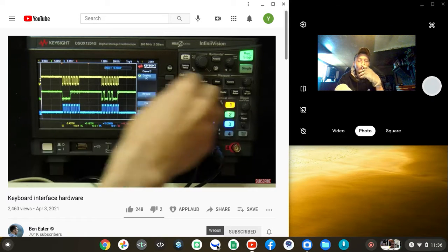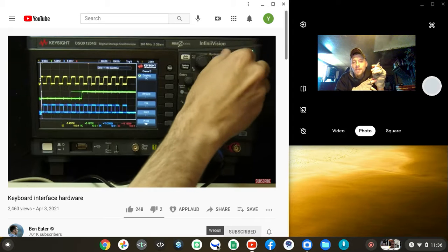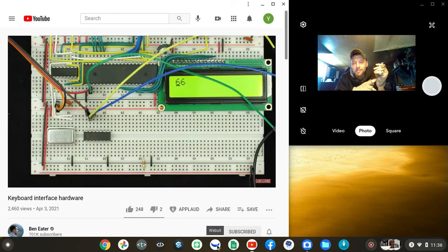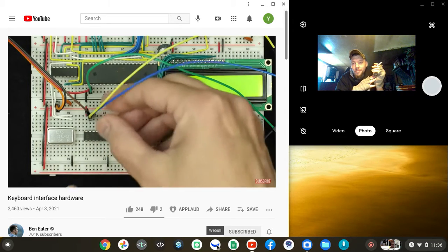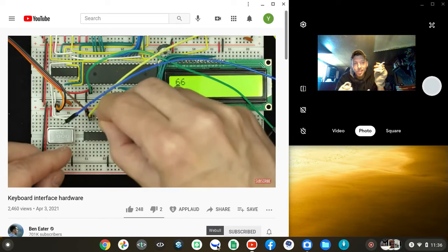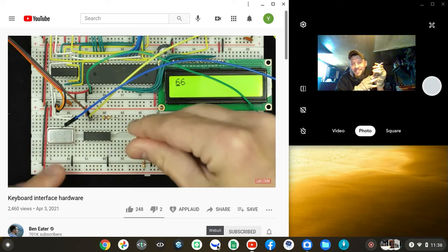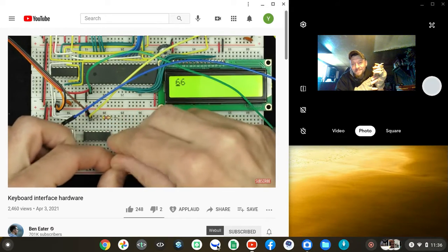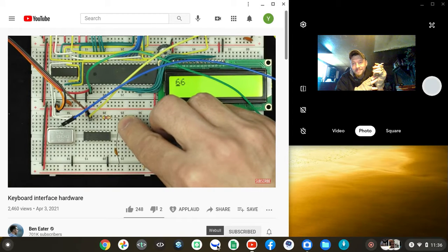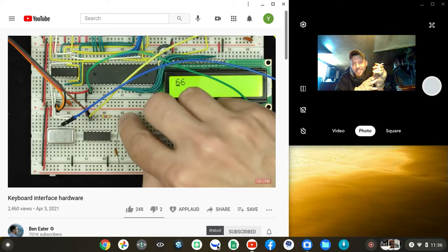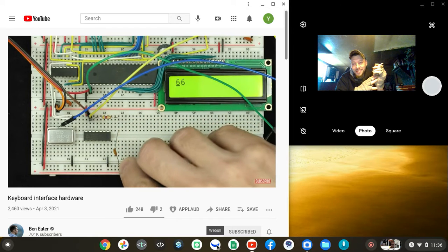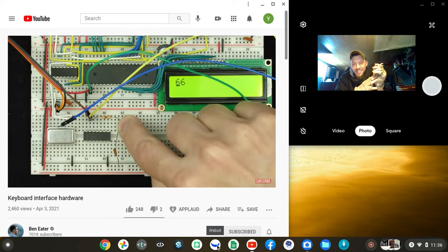So that's just the same as the clock pulse, but it's inverted. So let me zoom in there. So we're looking at a single pulse. And now what we can do with the output of this inverter is run it through a resistor and then a capacitor to ground. So when this clock pulse goes high, all of the current flowing out of that pin will flow through the resistor and essentially into the capacitor to charge the capacitor to ground. And so this point here will start out at 0.